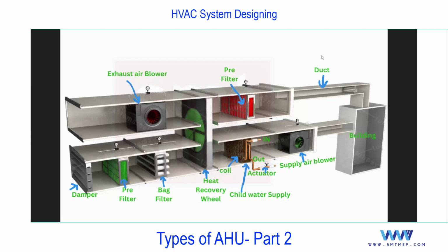We are recovering that energy which would otherwise be lost through the exhaust. So it's an advantage, where the temperature of the fresh air is lowered. So there will be less load on the evaporative coil. We did one project 5 years back, no, sorry, 7 years back, and we achieved 30% saving overall.